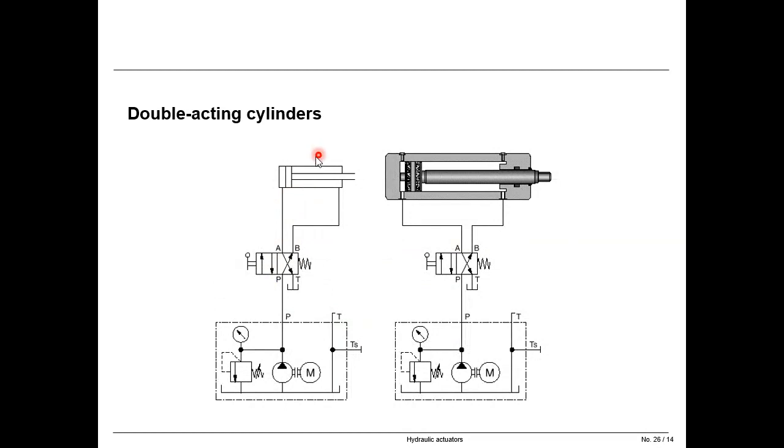So then we said, okay, how can we drive the double acting cylinder or double acting linear actuator? And we said we use a 4-2-way valve. We learned the 4-2-way valve, isn't it? Yes. Okay. So we use a 4-2-way valve to drive the double acting cylinder, and in this position, the piston makes the return stroke, and in this position, the piston makes the advance stroke.